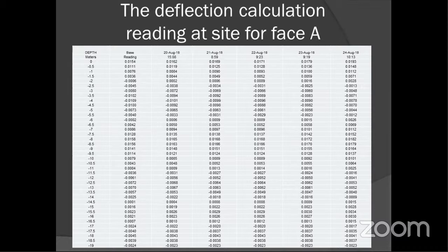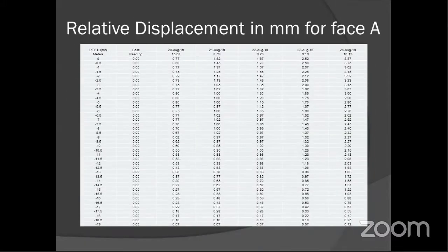After that, for the second reading, on 20 August, as the date has been mentioned, based on these readings, the deflection is 0.7, 0.8, 0.77, 0.75, like that. This is 0.77 mm. This is not even 1 mm, it is less than 1 mm. Like that, daily deflections and daily excavations happen, and this is how the deflection will increase.